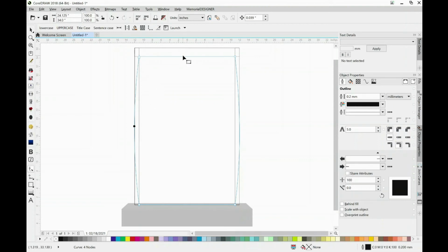This top line here, I'm going to do the same thing again, so I'm going to drag the middle up to the midpoint. But in this instance, I don't want an oval top, I want an OG shape. And in order to create an OG shape, I need to add an extra point in. So I'm going to add a point in there. And I can now move these angle lines to create myself my OG shape.